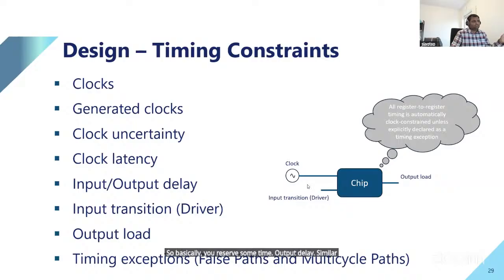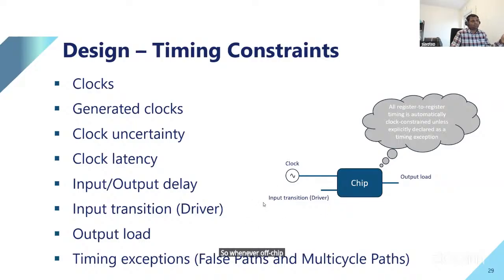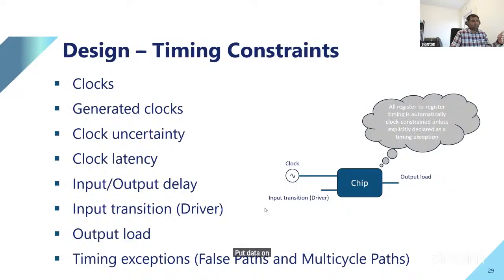Similarly, you reserve some time for inputs. So whenever an off-chip device tries to communicate to a chip, it will say, I will give you data, but I need some time to put data on this pin with reference to the clock edge.